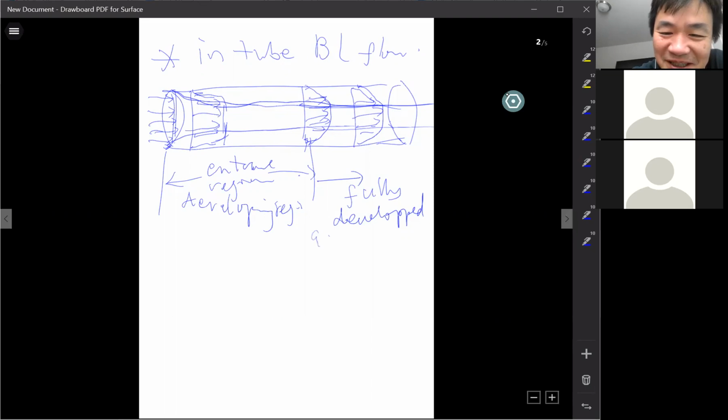99% for the free stream velocity, remember? 99% of the velocity, it doesn't change anymore, right? So if the fully developed profile has a region in the middle that doesn't change much, pretty flat, then you're sure the boundary layers are not meeting, for all different surfaces. But if your profile is like a developing profile just like this, you see, it keeps changing to the maximum. Then I think likely your boundary layer will meet, like that.